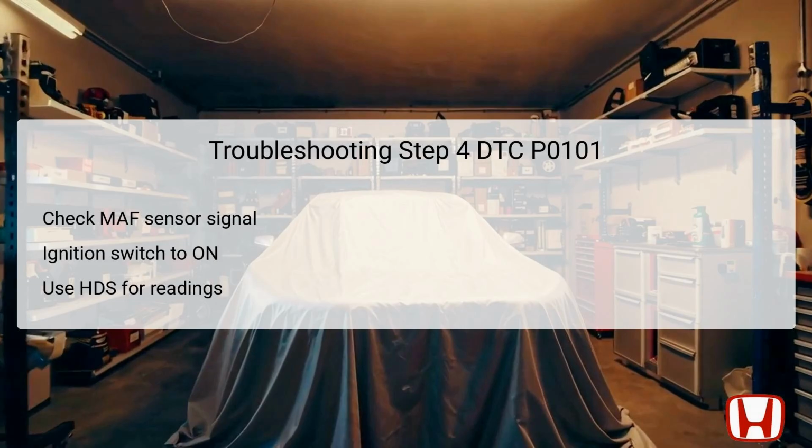Begin by turning the ignition switch to the lock position and then back to the on position, ensuring all electronic systems are activated. Utilizing the Honda Diagnostic System, HDS, you need to inspect the MAF sensor readings in the data list. Ideally, you are looking for readings around 0.2 grams per second, g/s, or about 0.5 volts.